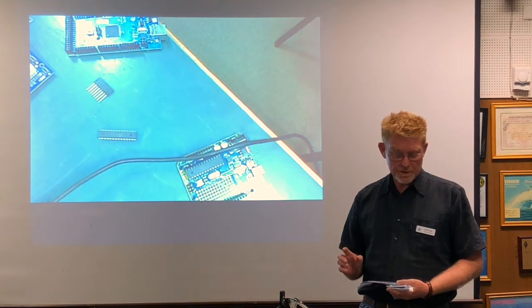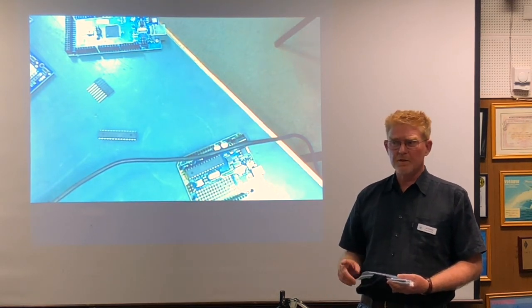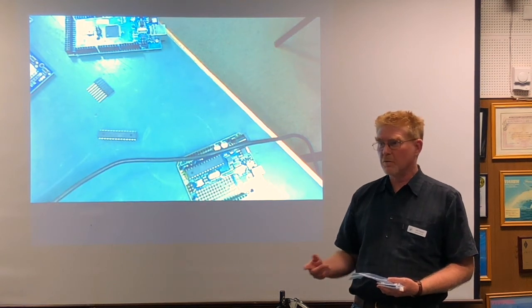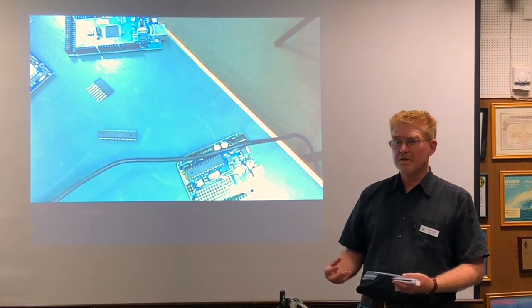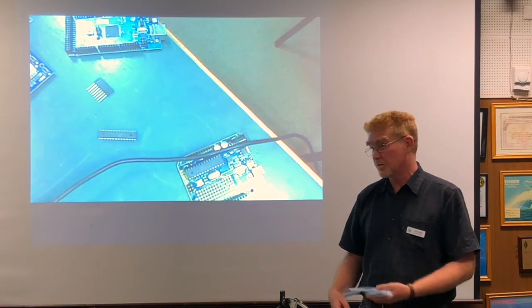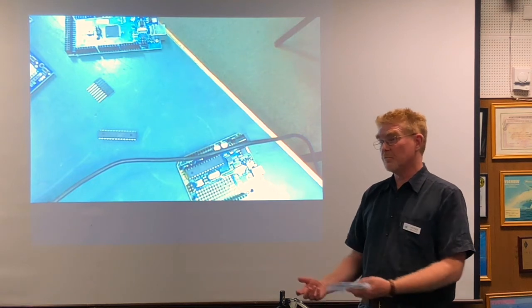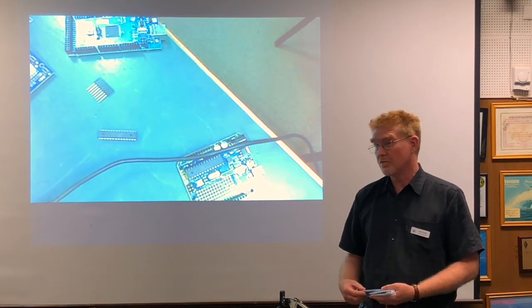Other options in that space, if you want to move away from the shield form factor, there's a company called Pololu who work in this robotics space, and they will sell you a stepper motor driver module which does all the hard work in terms of step counting and so forth, and speed and acceleration on chip. So again, use their libraries, use their module, and let them do the hard work for you.